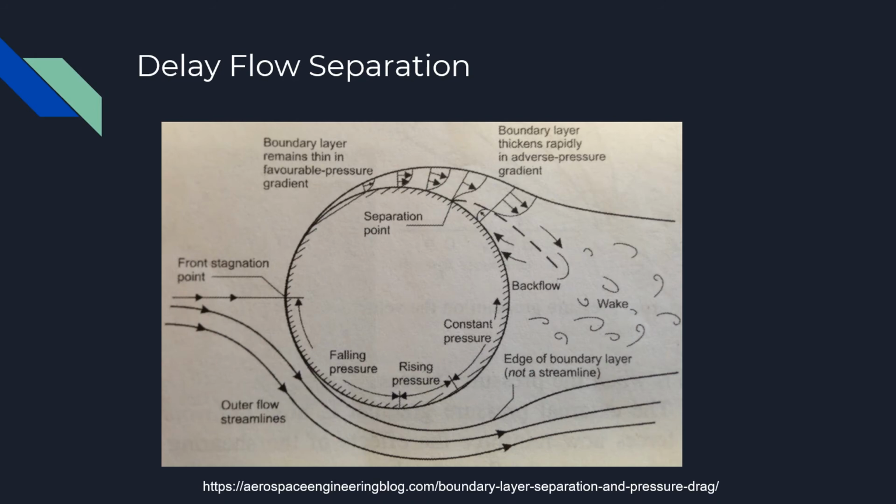At the front of the cylinder, the flow is accelerating and has a favorable pressure gradient as the pressure falls along a streamline, helping the flow to accelerate. The effect of this is to counter some of the friction effects and limit the growth of the boundary layer. After the widest point on the cylinder, this favorable pressure gradient no longer exists and the boundary layer grows quickly.